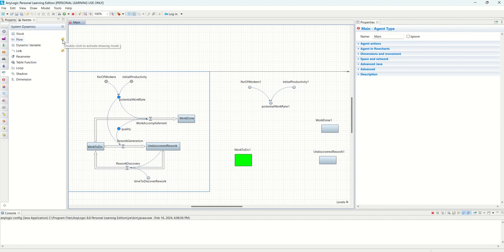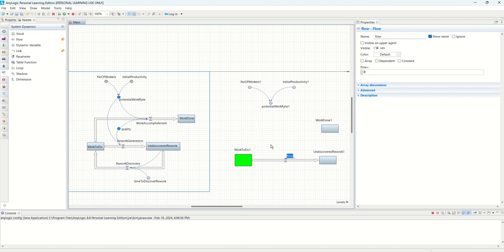So now let's draw our flows. Just double click it and then one click, second click. This is my flow. I'll rename it later. And then come here again, double click, one click, then you create a hinge for it here, second click, third click, and then the fourth. I know it's not looking pretty, so what we can do is just drag it and make it perpendicular. And flow, it's a bit tricky to adjust, so make sure you go exactly to the circle point here and then keep dragging it here.